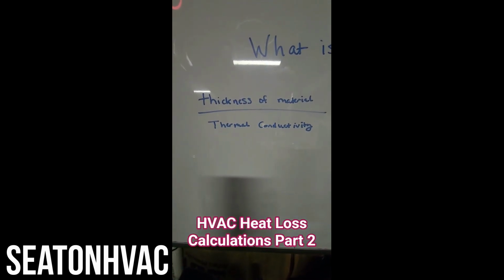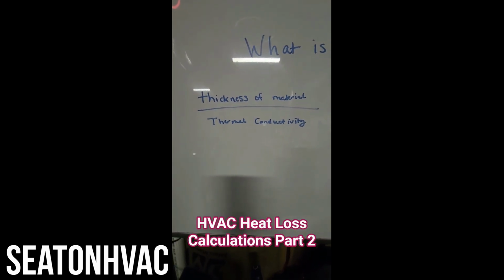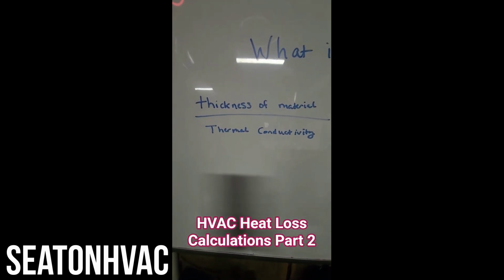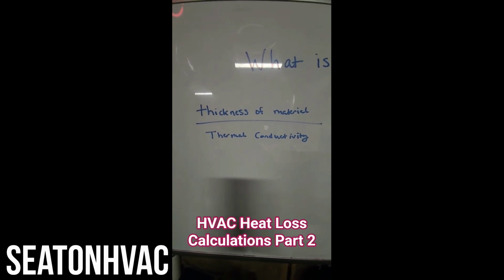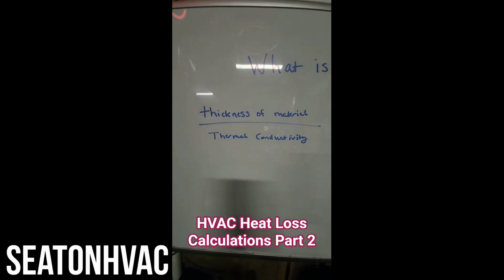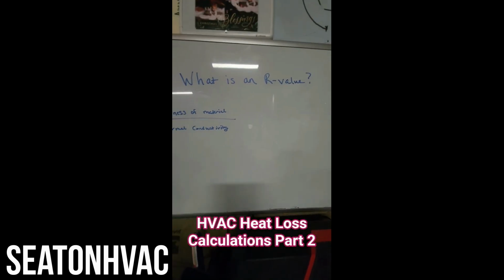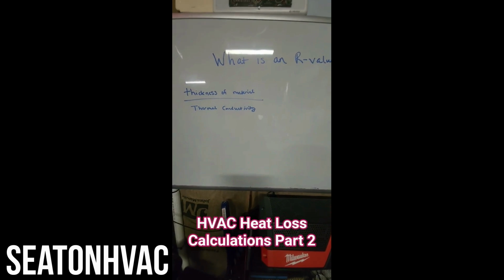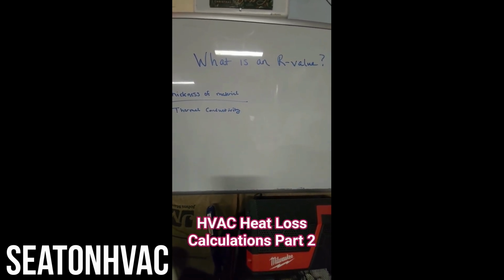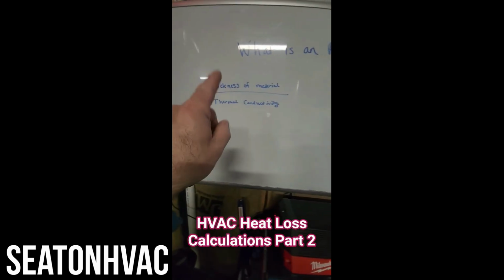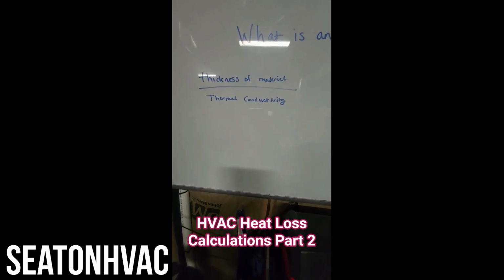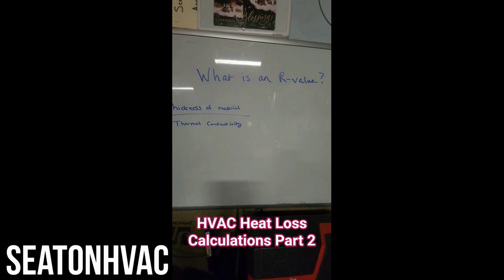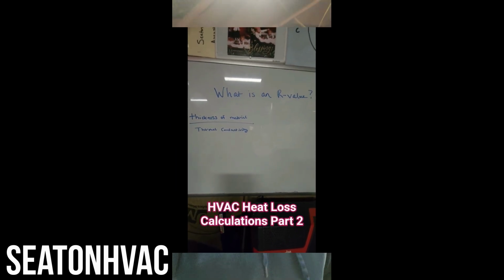But an R value is the thickness of the material divided by its thermal conductivity. So there's a whole formula to this. Each one of these has their own algebraic letter, I should say, and there is a formula to determine the R value. But what we're talking about here today is just things that you need to know. R value, and usually the product that you purchase or the product that you're looking at when you're measuring up a home is already going to tell you. So you don't really need to know how to figure it, but it's kind of cool if you want to get deeper into doing these calculations. So anyway, that's an important one, R value.